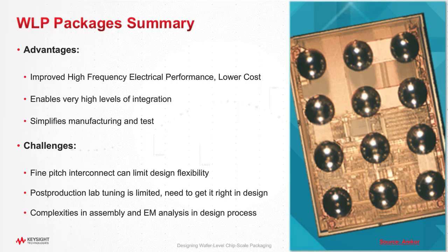There are some challenges. The first challenge is that fine pitch interconnect limits design flexibility. The way I think about that, I consider myself a microwave designer, so when I design, I feel comfortable designing 50 ohm transmission lines and nice thick metals. When I look at chips and interconnects, like you'll see on wafer level packaging, these start to look like what I would consider parasitics. So you don't have the ability to create these really well controlled lines, and when you get to high frequencies, you have to think about that a little bit more.